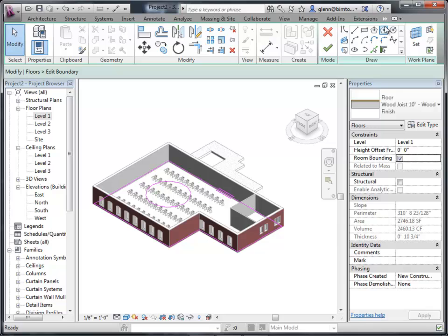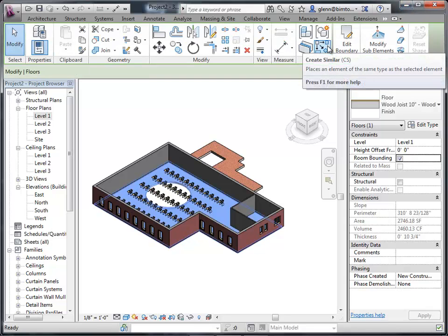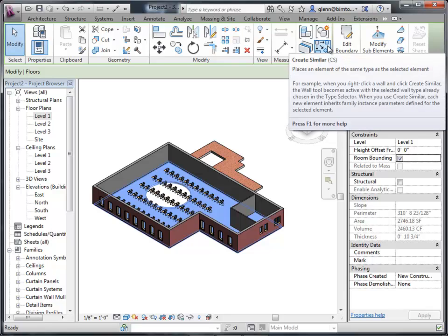Okay, that is floors. Let's get you going with floors there, and let me give you a real quickie on roofs, because roofs are going to be so similar to floors, you're actually going to start thinking of them the same way. The only real difference you have to think about relative to roofs versus floors, and here's the wall again. So floor, bring it on into the core, that's all good. With roofs, there are two things you have to worry about. One is that typically we don't stop right at the wall. We have some sort of an overhang.